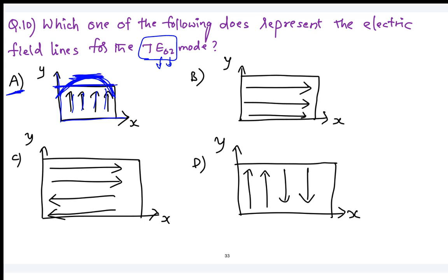So when you move along the X direction, you can see that all the flux lines are oriented towards you. Since all are oriented in only one direction, you can say one variation is there. So this is an example of TE10. When you are moving along Y, are you able to see in which direction the arrows are oriented? When you are moving parallel to the flux lines, you can remember there are no variations.